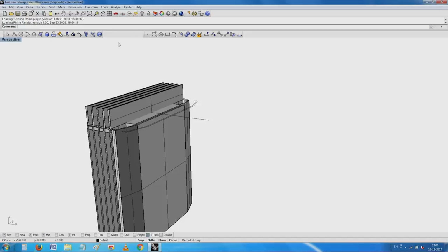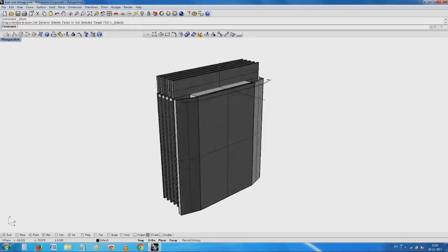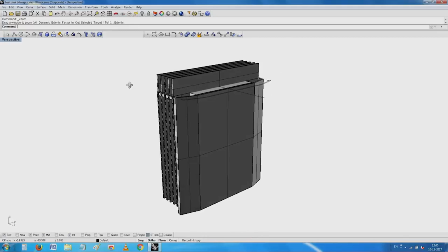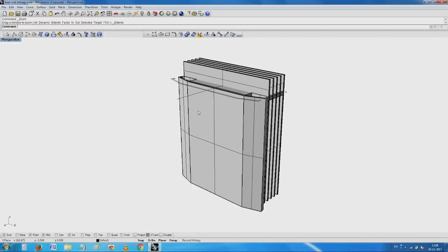You see here at this point, I have used the commercial heatsink and tried to build an equipment. In the last lecture, how well can I make an equipment which looks like this. This is about the concept design, and secondly, most manufacturers' catalogs will give you, given a length, what should be the thermal resistance of the device.